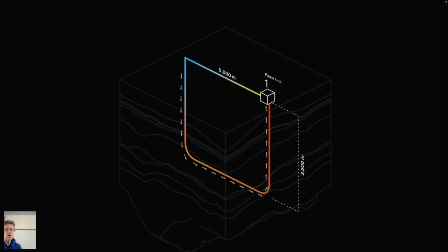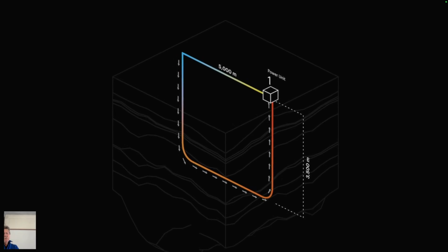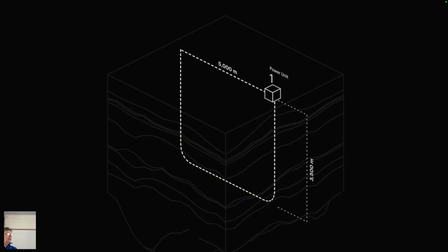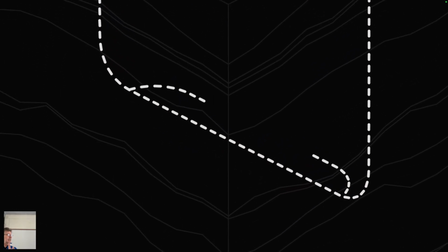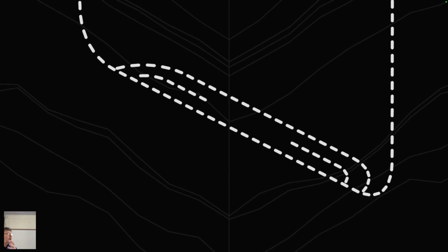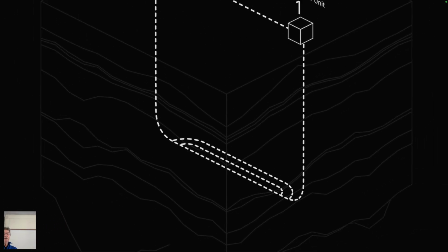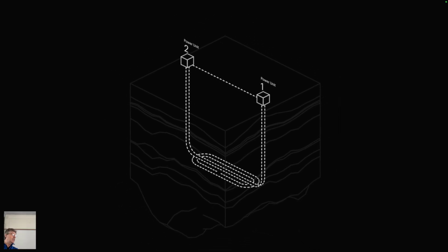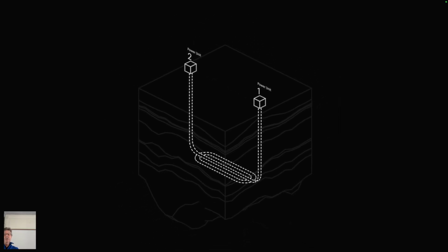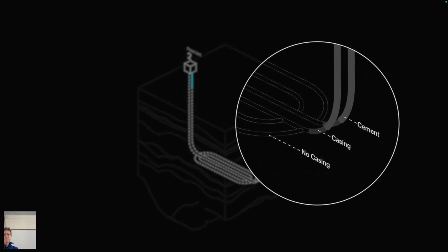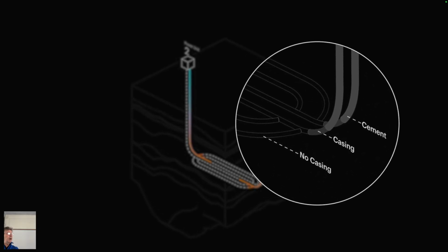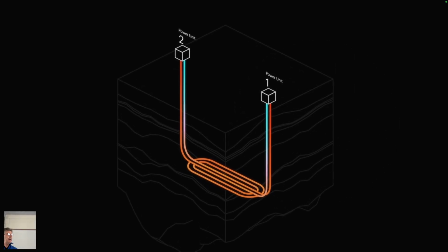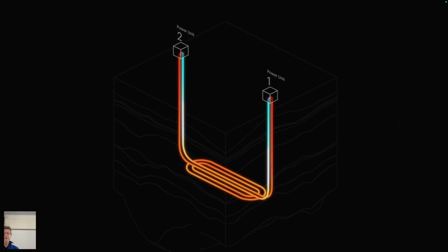They inject blue cold water into it, or a heat transfer fluid. That gets heated up as it goes across the circuit, and as it gets to the other side, it's hot, it's less dense, and so it will rise buoyantly. So they make the case that if you have a heat transfer liquid which changes density a lot, such as CO2, then it will change its buoyant force a lot, and it will want to rise, and you don't have to expend any energy actually pumping, because the so-called heat pipe effect means that it will drive itself naturally.